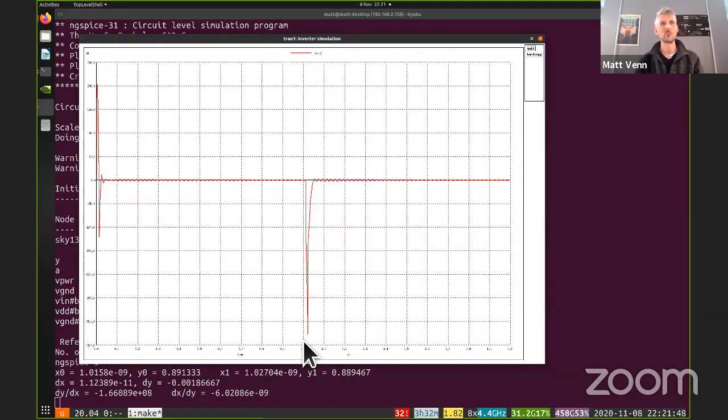So we can see with CMOS, the current only is used when we're changing state. And this is something that I've been doing electronics for a long time, but I never really thought about this before until I did this. So it was really interesting for me to realize that when you put your chips in low power mode, often what you're doing is doing clock gating. You turn off all the clocks, and then none of the logic can change state, and so your power doesn't get used.